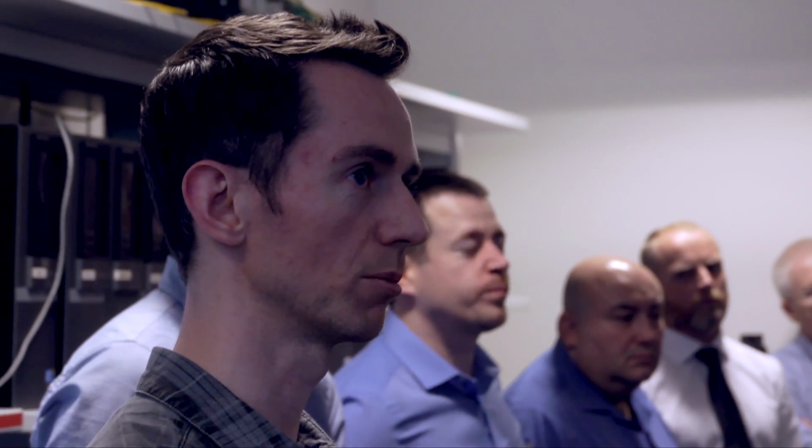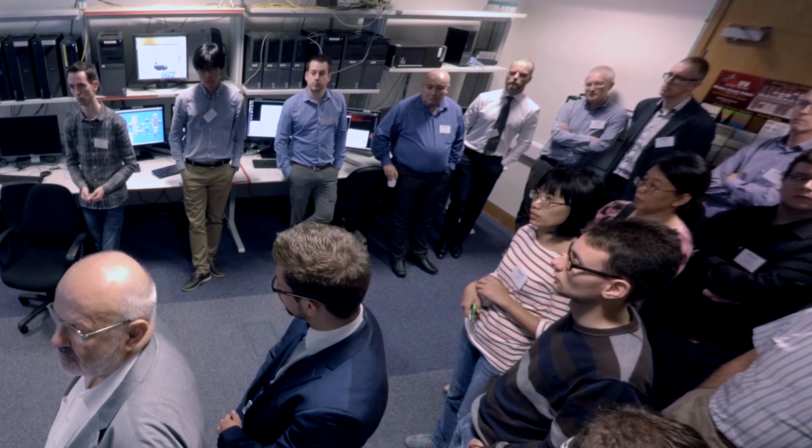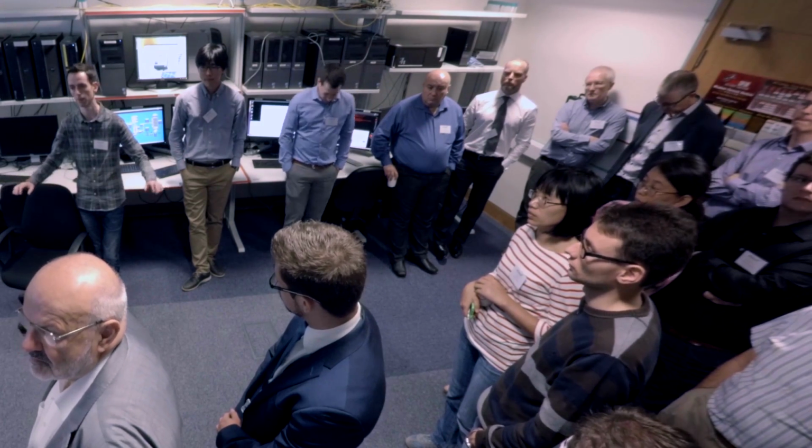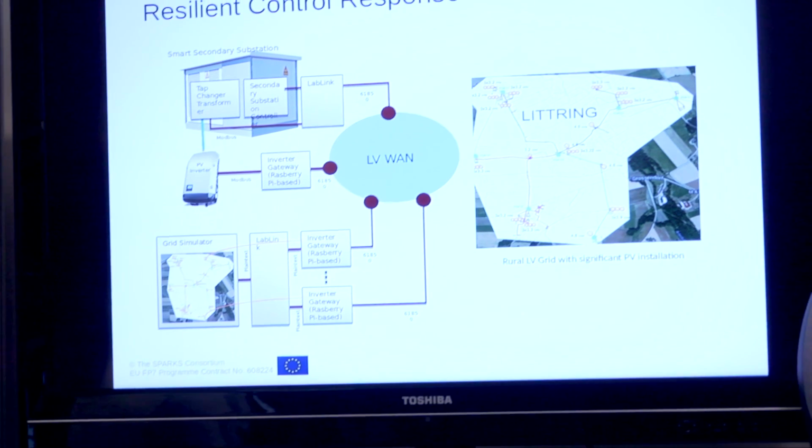And the setup there is thinking about the future smart grid. So not just the grid today, the grid tomorrow, imagining it's maybe more federated, so the grid can be composed of different microgrids. It could potentially also have a lot more embedded generation. So here we're thinking about a lot of solar generation, it could be wind. So going from a big monolithic system to something that's got more distributed generation. The use case here is that the PV arrays are being used for voltage management, changing the reactive power from the PV to adjust the voltage depending on the current state of the system.